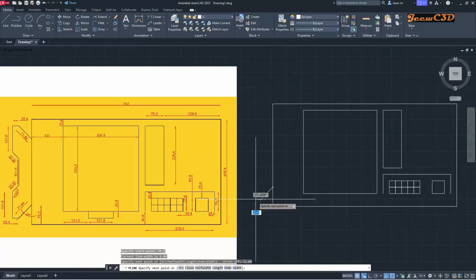71.84 and press enter. Now that is completed. Now you have to go this way. It is 25.4 millimeters. I press enter. Now to upwards you have to go. Now I am going upwards using the object snap tracking.